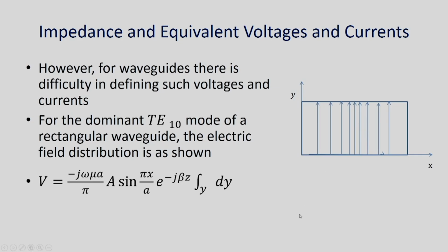So, what we find is that if we consider this type of single conductor transmission line like a waveguide, we cannot uniquely define the voltage, and the voltage will vary depending upon where this voltage is evaluated. So, voltage depends on the position x for this type of waveguide.